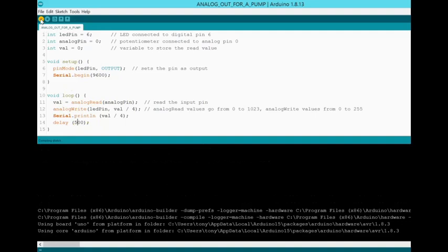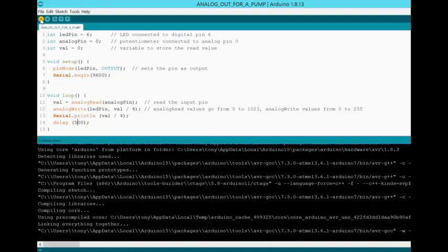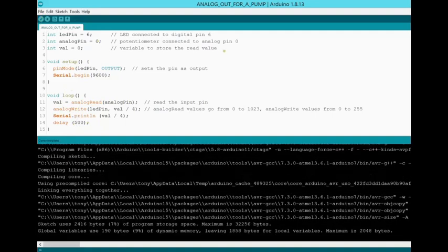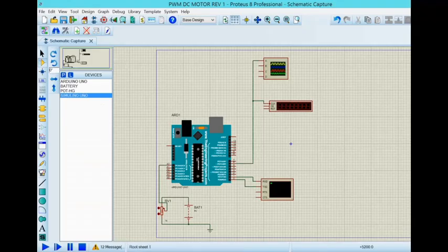The nice thing is that since I already have connected my IDE with Proteus, if I make changes here, I don't have to copy the hex file. It's already there and it's already alive. So when I do my run, it will pick up the newly built code.